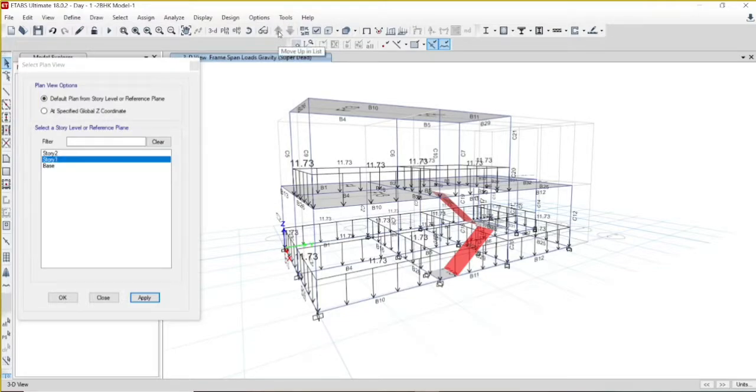Okay. Also you will be having a parapet wall. In all the first floor you will be having a wall which is 1 meter high for safety purposes, and throughout all the first floor you need to apply the parapet wall. If you are having the first floor and this is the second floor, if the structure needs a second floor and the opening at the second floor, you can add the floor here, and the staircase can also be extended up to here, and you can add a parapet wall. So as of now we will be only providing the parapet wall at the first floor only.